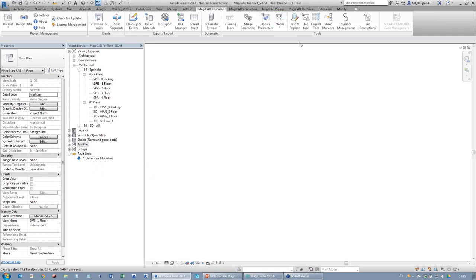Find and replace. When you draw with regular Revit and you place something, and then you go into the properties and just replace it with something else, sometimes you will lose data. For instance, when you draw ventilation, you can lose the flow on the air terminals and so on. With this find and replace tool, you don't lose anything.